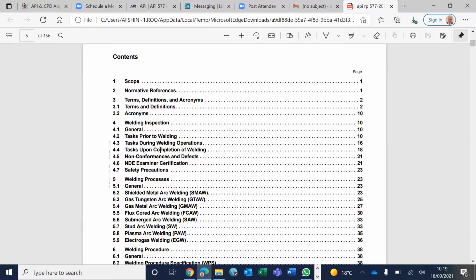And during the welding operation, you check the preheat, the heat input, the welding speed, and then when each process is done, you do a visual check, make sure there is no high-low. And then at completion, you do a visual check that the high-low and the crown are within the permissible, and whether there are any welding defects, spatter, that sort of thing, undercut.